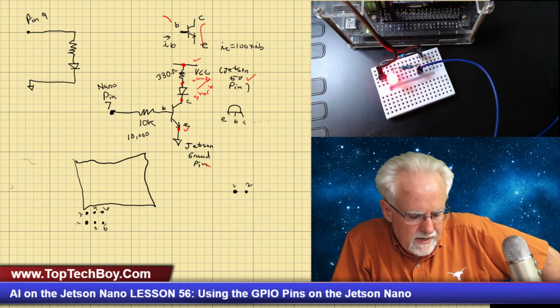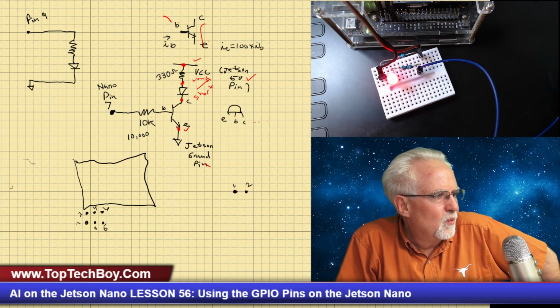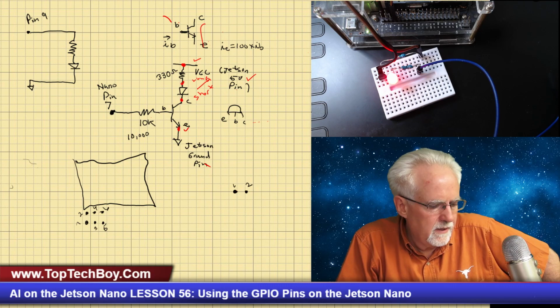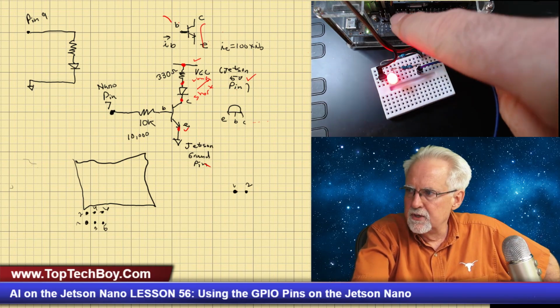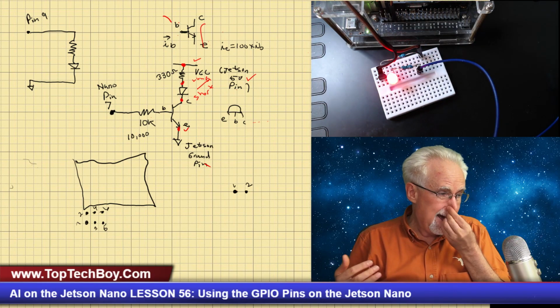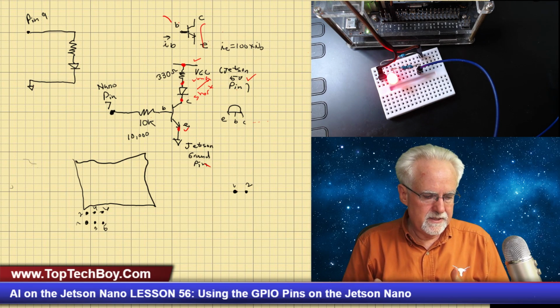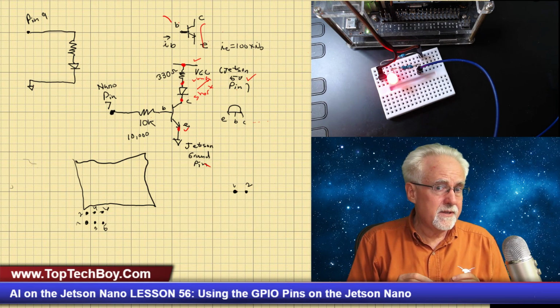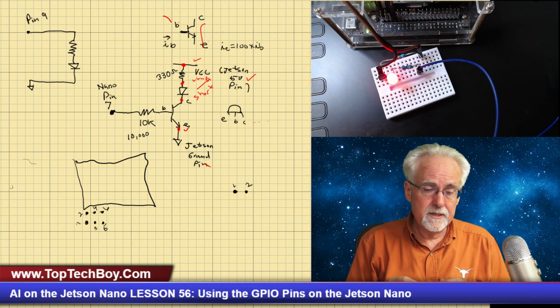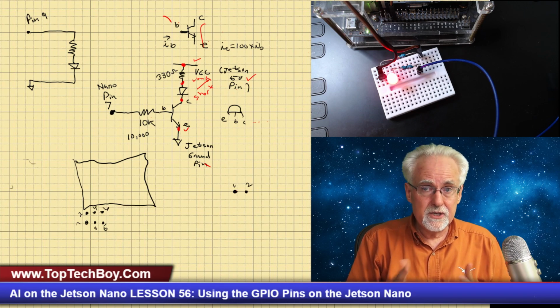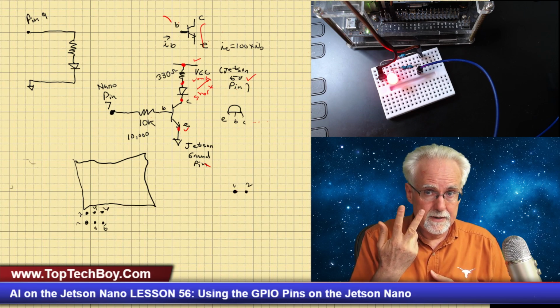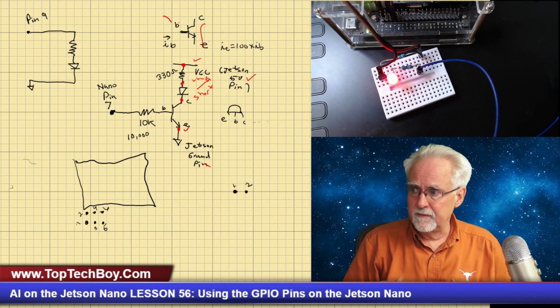The first thing that I did was I looked and I saw that I was sending commands to pin 11 where physically I was hooked up to pin 7. I corrected that mistake, but it still didn't work, and so I checked the circuit connection by connection, and then I see, the connections are right, but it must be the diode. I turn the diode around, and then everything works.